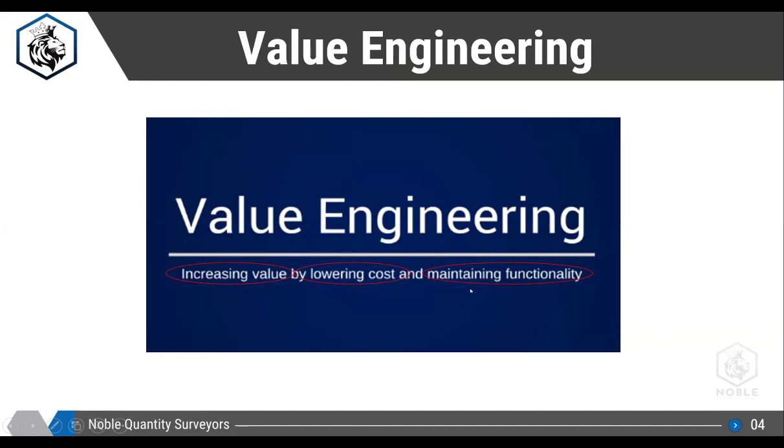Somebody will ask, if the consultant is asking for copper pipes, we have to use the copper pipe for the buildings where it is necessary. I'll give you an example for hospital works. If you're doing any hospital building, there you have to use copper pipes. You cannot use an alternate material like UPVC pipes. But if the copper pipe is specified for a residential building, there you can put an alternate material, like PPR or UPVC. You cannot change copper to UPVC for a hospital building.